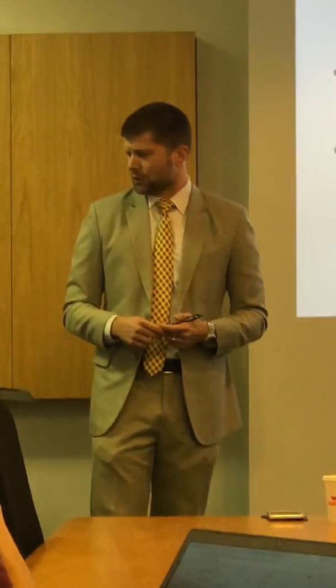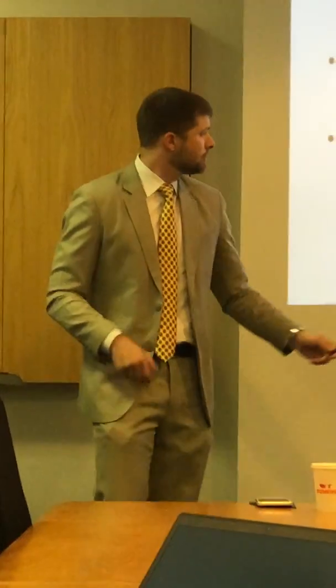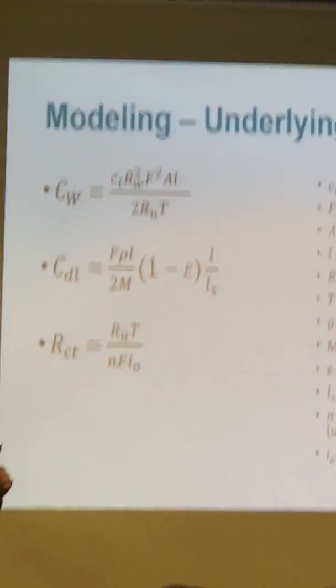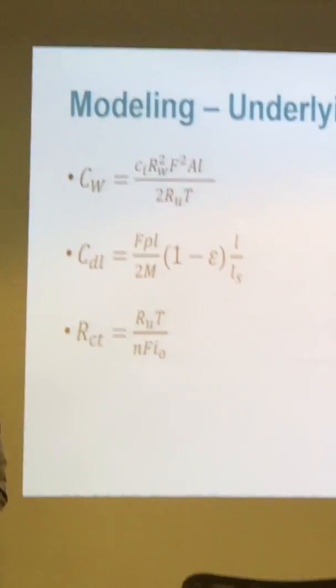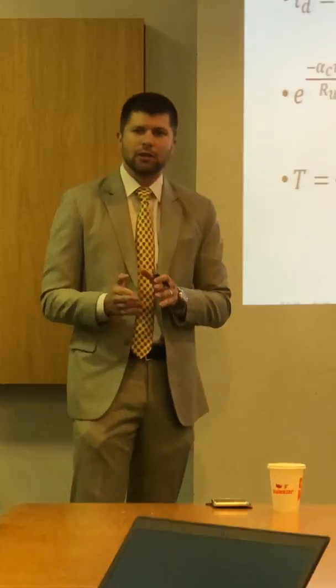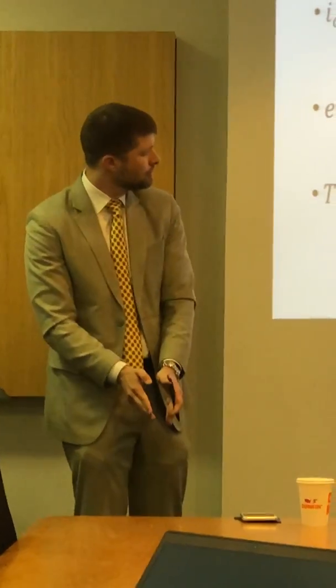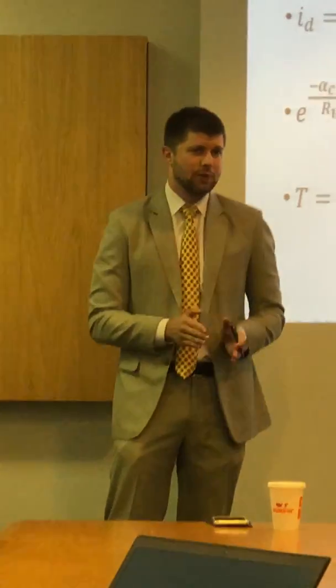The charge transfer resistance is a function of the cell's ambient temperature, the number of ions in the electrolyte, which is one for lithium, and the exchange current. And now the Butler-Volmer equation. As we said earlier, we found that somehow, with the cycle life study, the dynamics inside the cell as a function of current are proportional to those as a function of temperature.